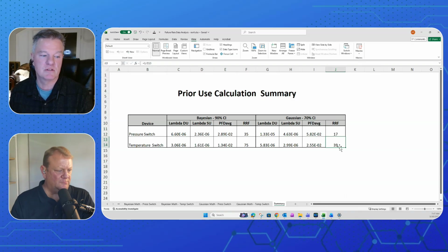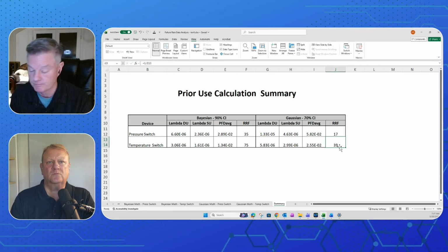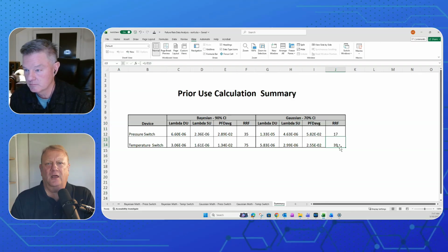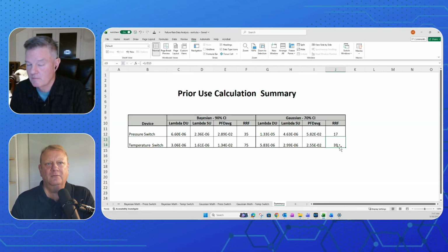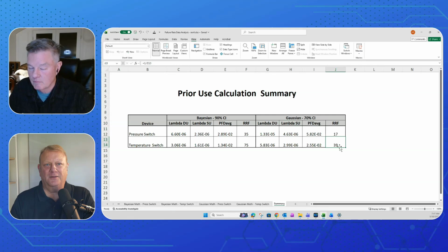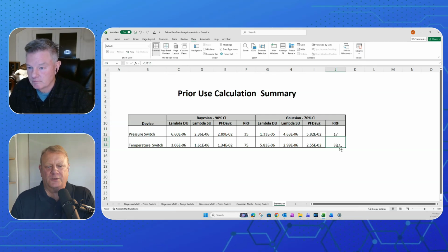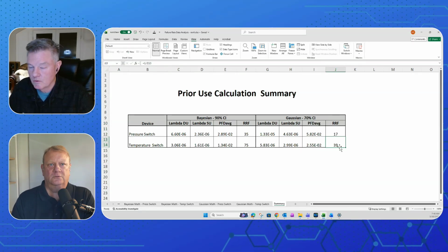Yeah. So this is easy to do, straightforward. So summarizing it, then you're collecting failure rate data. You're analyzing that failure rate data using known formulae that have been provided by people that have studied this stuff. And you're coming out with results that allow you to extend your test interval. Correct.